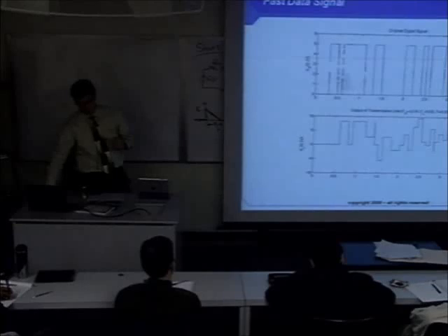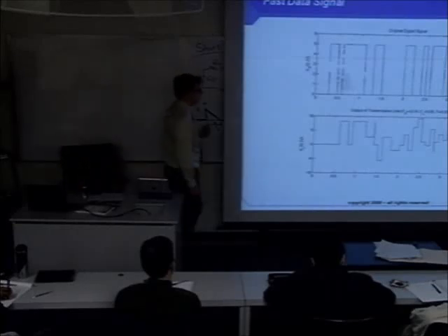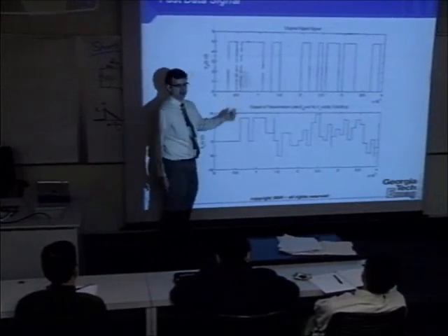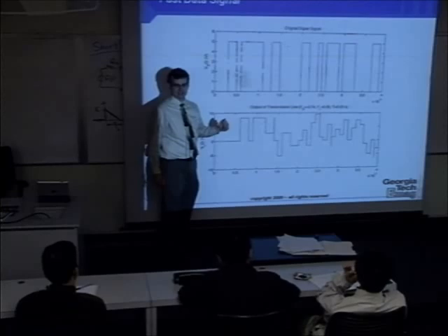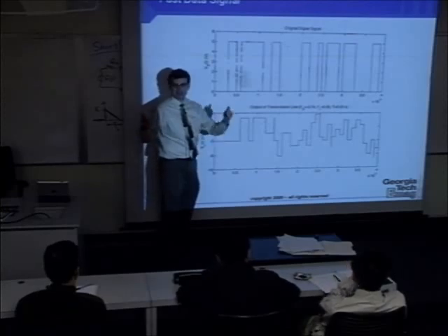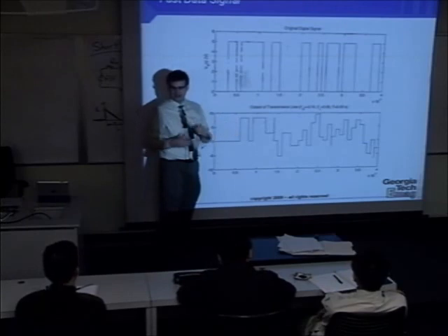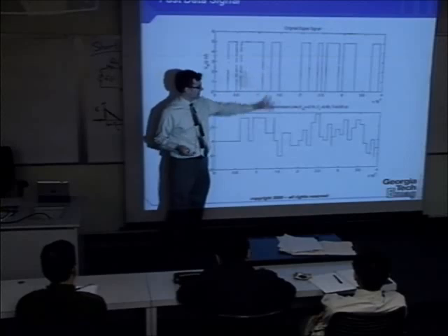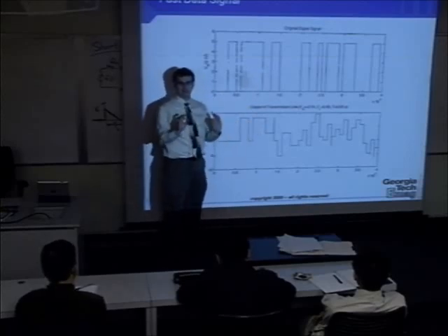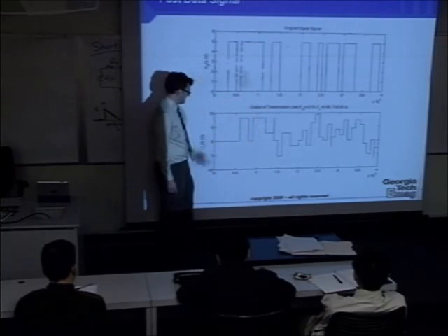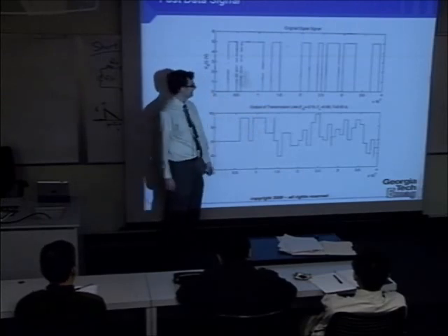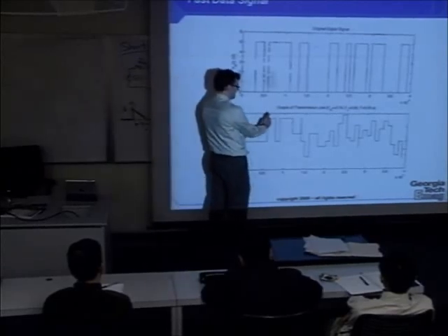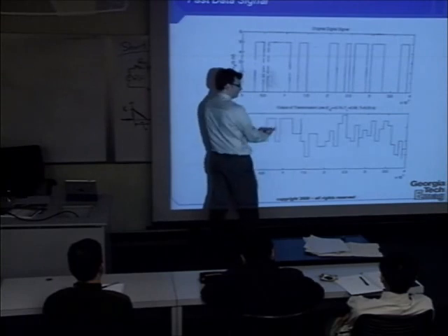It gets worse, though, when you start to look at symbols that are very small with respect to time. This is in the pulses that are in the tens or hundreds of nanoseconds. Pretty high data rate. This is the tens of megabits per second type data frame. And look at what the convolution of this digital sequence is with that exact same impulse response. I can't even recognize anything. It's going all over the place. And in fact, literally the echoes, even one echo on this line is jumping into another time slot.